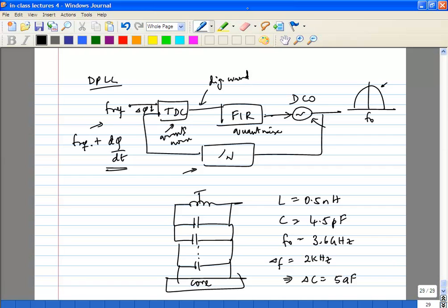Okay, so I have shown a very simplistic view. What you will typically have is some kind of delta sigma inside, which will dither very well between these caps, so that you can do noise shaping, some amount of shaping, such that your average is exactly at the frequency where you want to set it.